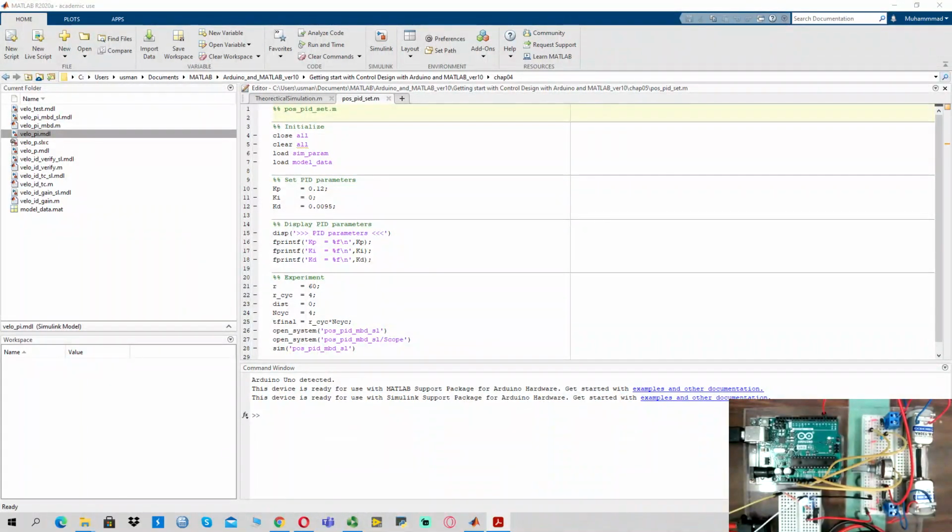In this experiment we'll try to give students a little bit of an overview of feedback control theory, which will include basic proportional control and how we can implement it on the motor speed control setup, and also integral control to eliminate the steady state error, because proportional control is not able to remove the steady state error in your system.